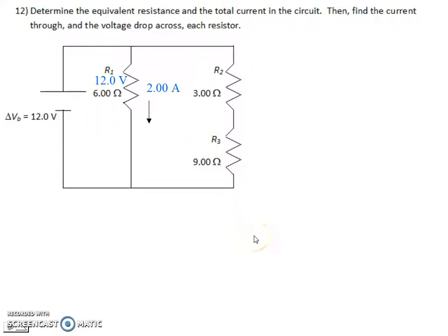So here it's a matter of choice what you want to do, but let's try to do it the same way we were doing before. We know there's a total of 12 ohms on this path. So imagine, or you can redraw if you'd like to, replacing these two with a single 12 ohm resistor. Now 12 volts has to be dropped by the combination of 12 ohms, and so 12 volts over 12 ohms, that's got to be 1 amp of current. And they're in series, so they're each going to have the same current.